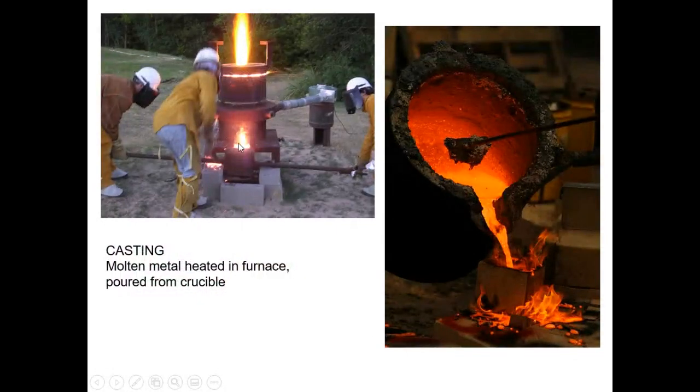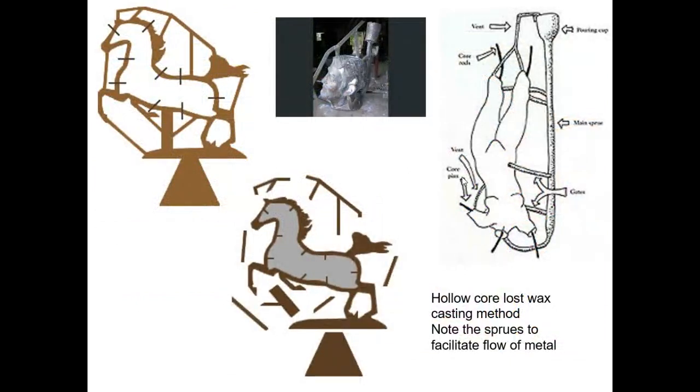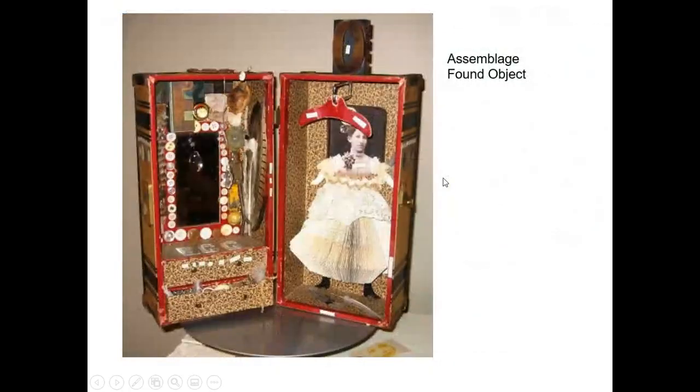Then we would heat the metal up until it becomes liquid, put it in a crucible, and literally pour it into the opening in the mold. Therefore, the metal would replace all of where the wax had been. And once it's cooled, we would smash the mold off, and you'd have an object like this. So you would have to then cut off the metal that had filled where the sprues were, as well as the pins themselves, in a process called chasing.